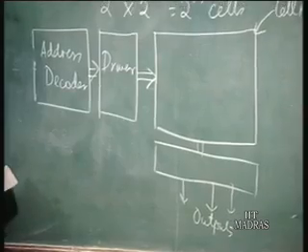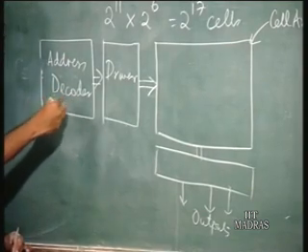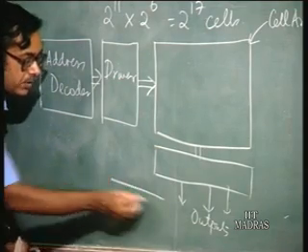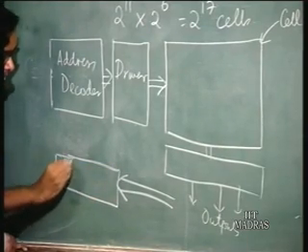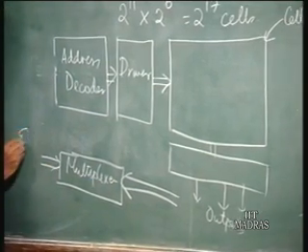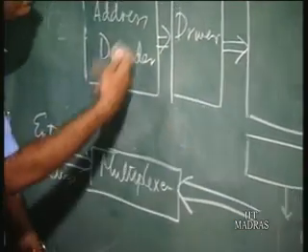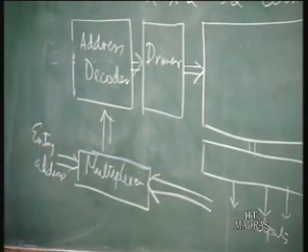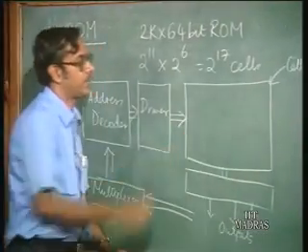In this particular case, this is where you store microcode, because any instruction may have more than one cycle. So, the output part of it is fed back again to the next address input. You have a multiplexer, which either takes an entry address, a new address, or the fed-back one, in this case 11 bits, because it's 2 to the power 11, as input to the address decoder. So, this is the basic structure. Anyway, what we are interested in is the memory.